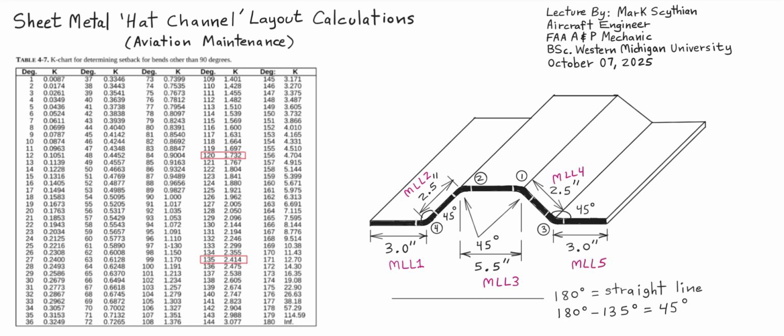To be a little more specific here, we have to take the flat plus bend allowance, flat plus bend allowance, flat plus bend allowance, flat, bend allowance, and flat. And so when we add up this summation, we will have the unbent length.